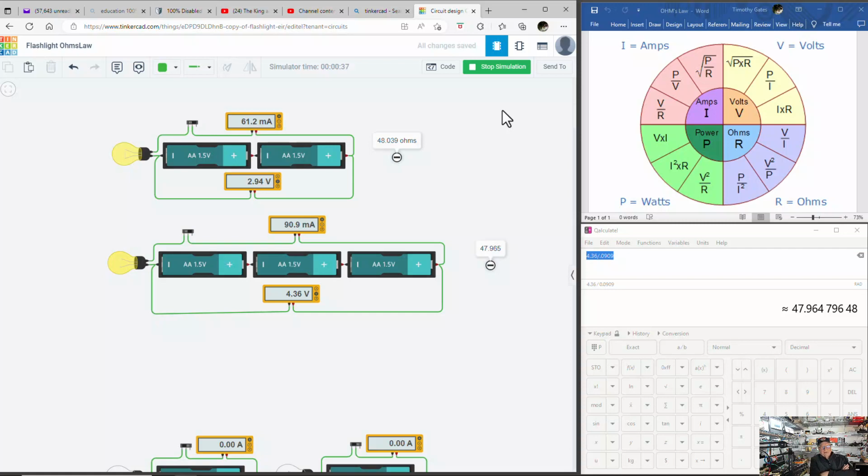Almost all materials that will conduct electricity have a temperature coefficient. If it's a positive temperature coefficient, then the resistance goes up with temperature. But in this case, it went down, right? Wouldn't you say that 4.5 volts is going to make the light bulb hotter, increase the filament temperature higher than 3 volts, right? And the resistance went down, which means it has a negative temperature coefficient.